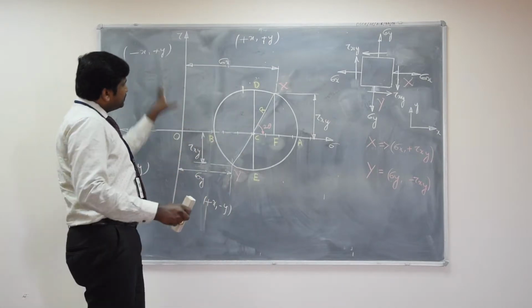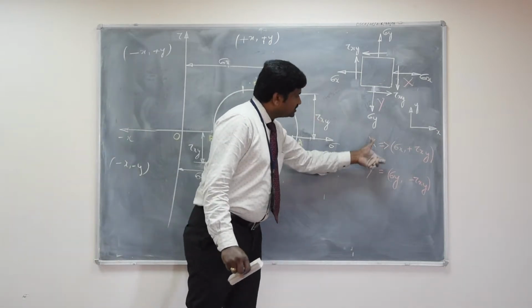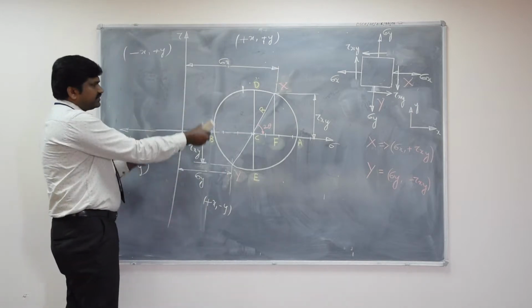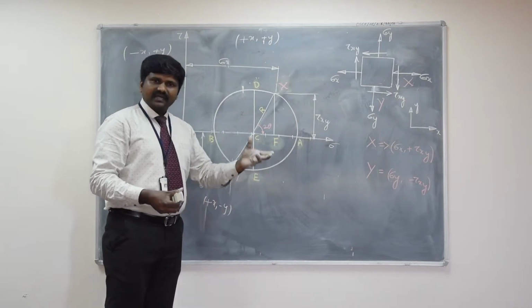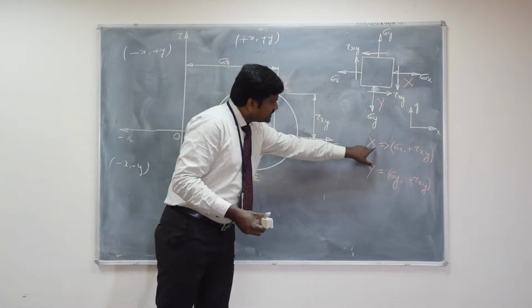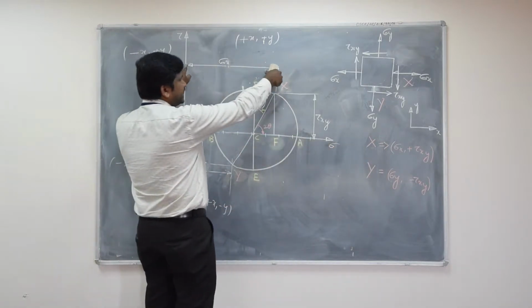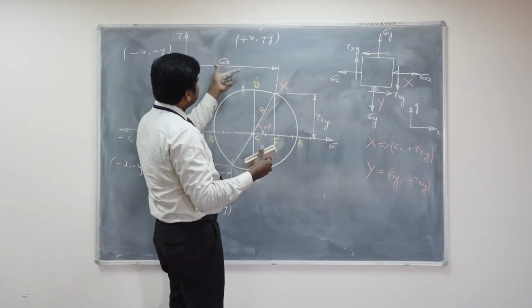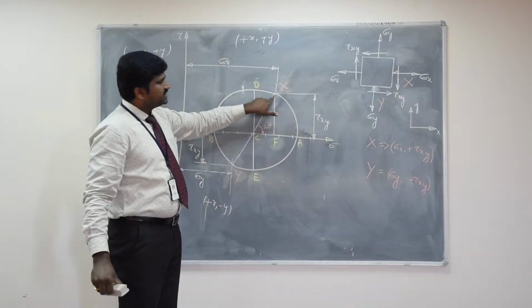That means if you remember this sign convention, you can easily locate these coordinates on a Cartesian coordinate system. So here I have taken first an example, then we will explain once again with the proper example so that the concepts are very clear. Now, these x coordinates are represented here. This is the sigma x distance, and this is the tau xy distance. So plus sigma x, plus tau xy. These values are represented here.